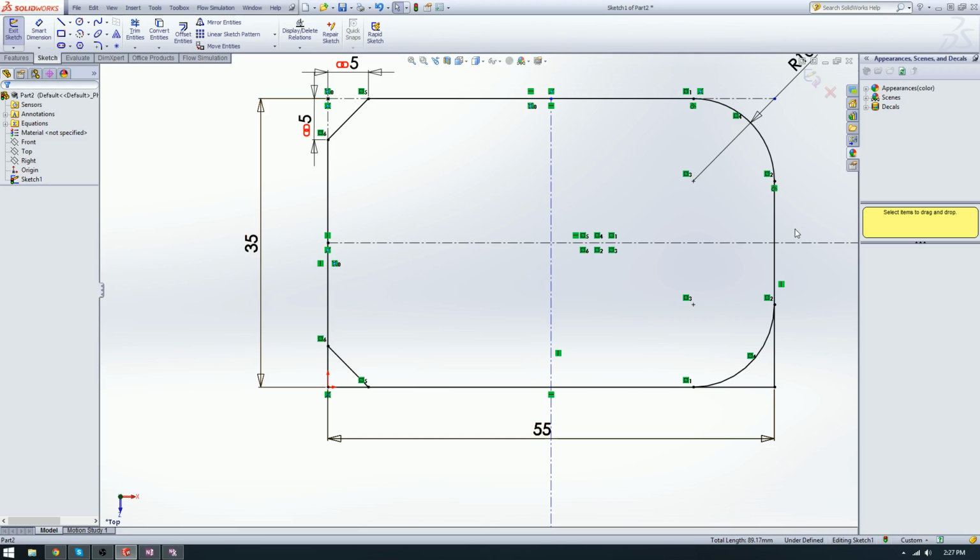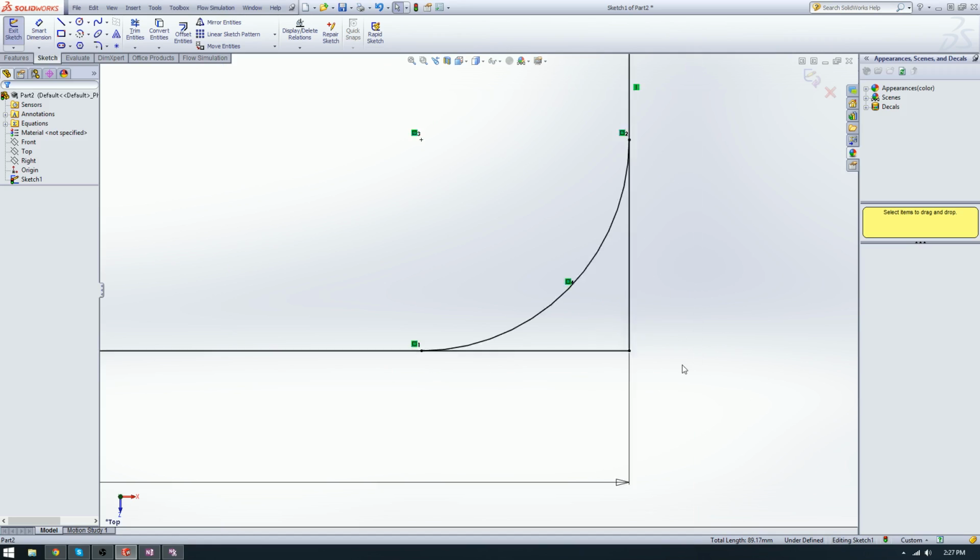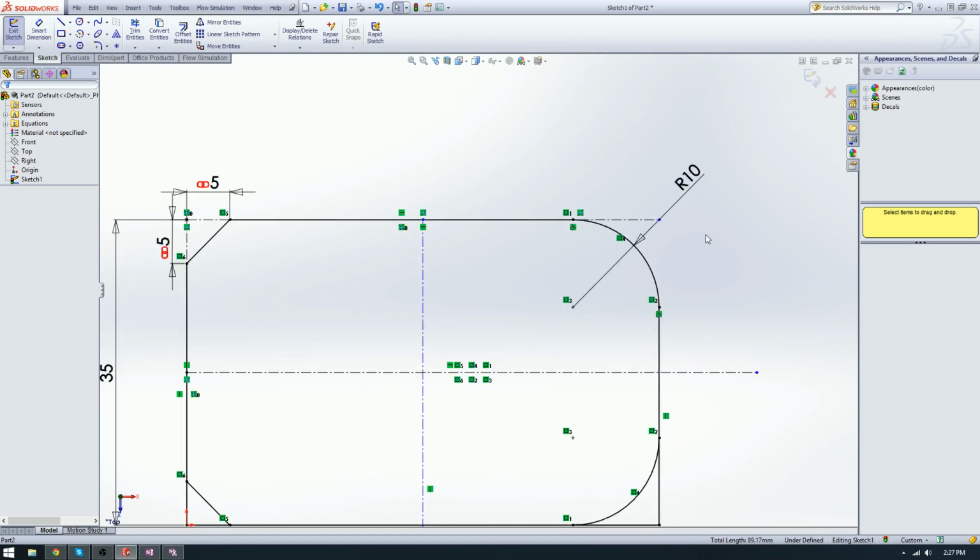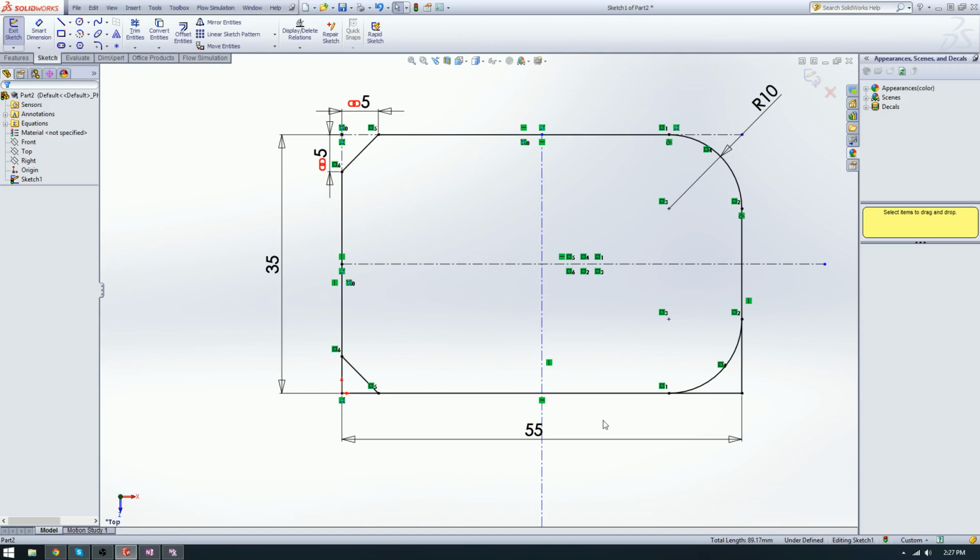Now we have this beautiful new fillet and a new chamfer. Okay. Now we have this extra line over here. We don't want this. You know, let's say we want it to look like the top. Now, why did this happen? When we did the fillet, basically, it automatically trimmed these for us and set new relations. Now, this is something you want to be very careful about when you mirror things. Not everything works correctly. It should, but it doesn't always work correctly.